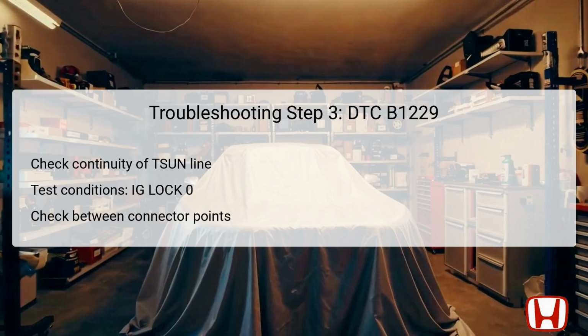Should there be continuity, it confirms the wire is operational, allowing for progression to the final troubleshooting steps. If no continuity is present, an open in the wire needs to be repaired, restoring the circuit before proceeding.